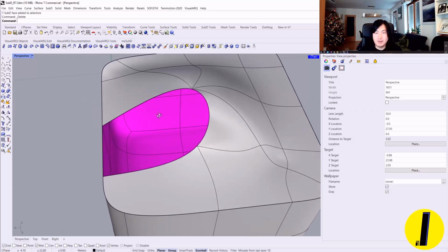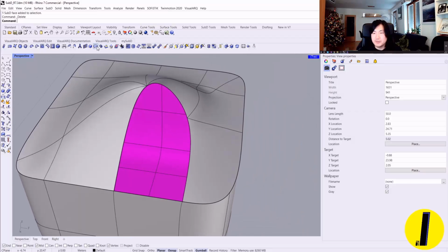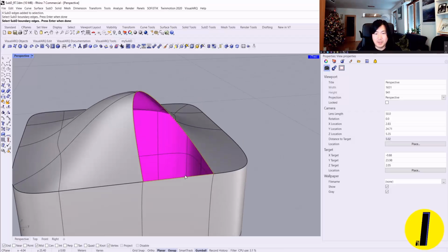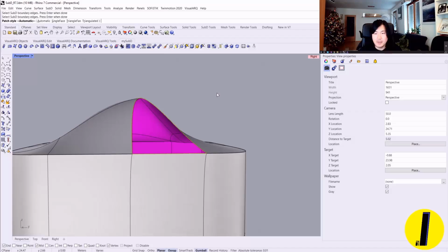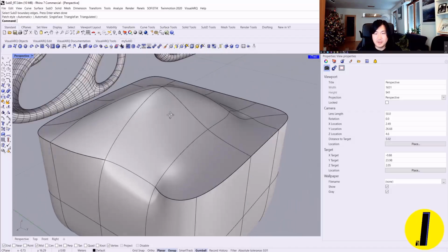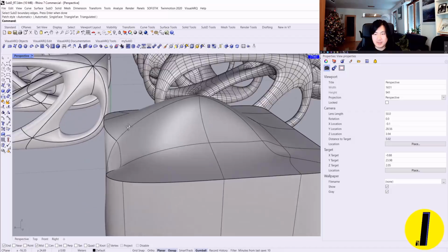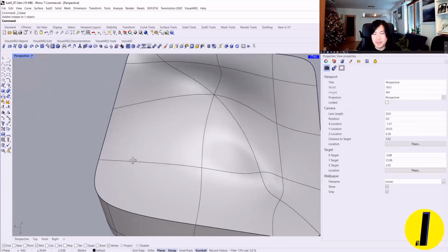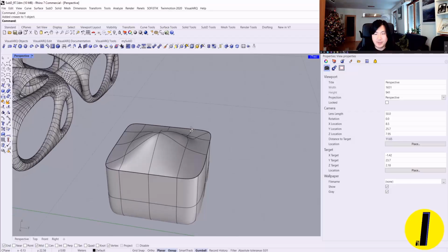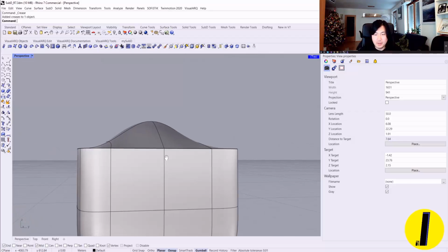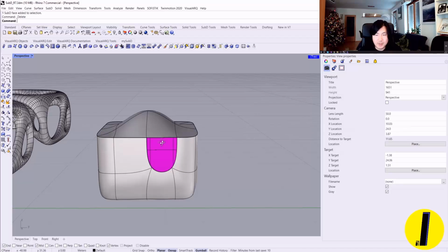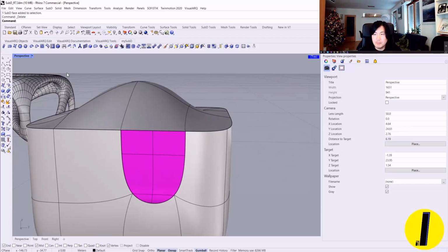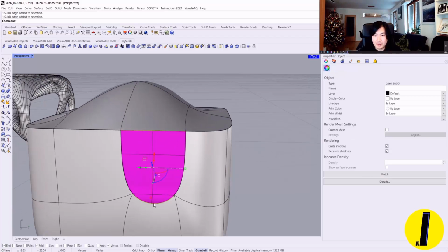There are a couple of ways we can fill the hole. Perhaps we can use this Fill SubD Hole tool, and we can select all this boundary where the hole is, and when you hit enter, you can see the hole is filled, but because of this we lose the crease. If I add a crease, then we come back to the original shape. Or another solution could be, let's say we removed here, and we could perhaps bridge two edges here and there.